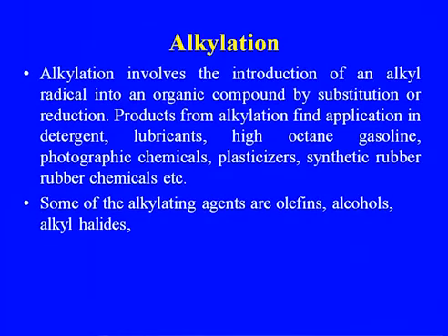Alkylation involves the introduction of an alkyl radical into an organic compound by substitution or the reduction. Products from alkylation find wide application in detergent, lubricants, high octane gasoline, photographic chemicals, plasticizer, synthetic rubber chemicals. Some of the alkylating agents are olefins, alcohols, alkyl halides. Here actually in case of the alkylation process, that is now we are using in case of the petroleum refining and the petrochemical industry both, alkylation for producing the high octane gasoline,